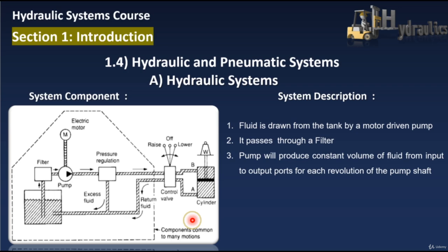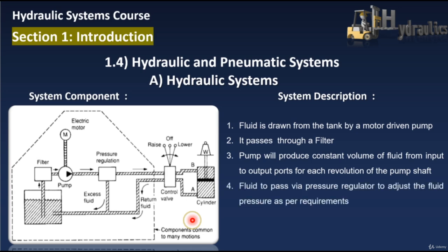Such a high pressure pump, however, cannot operate into a dead-end load, because in that case the fluid pressure will rise indefinitely until the pipe or the pump itself fails and the system collapses. So some pressure regulation, as shown here, is required to spill excess fluid back into the tank.